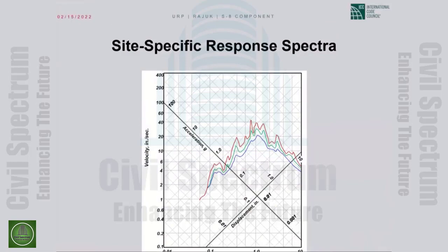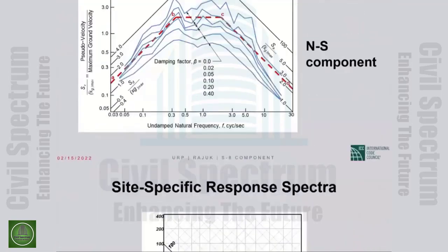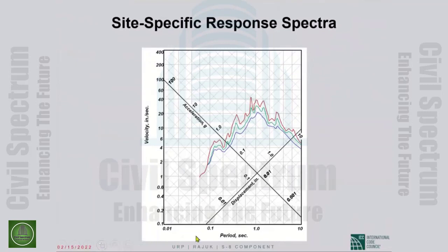So we have gone from the Newmark plot to one of our plots where period is on the x-axis. Spectral pseudovelocity is, as always, on the y-axis. Here we have shown the spectra still for the north-south component of the 1940 El Centro ground motion. We have the spectra for 3 different amounts of damping, I believe 2, 5, and 10% of critical damping.